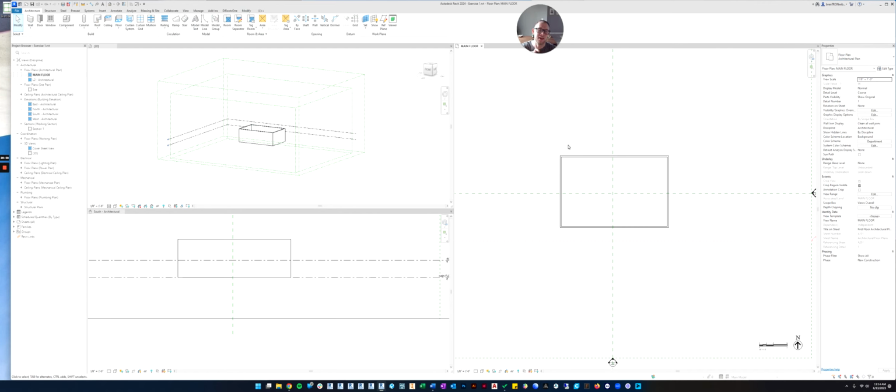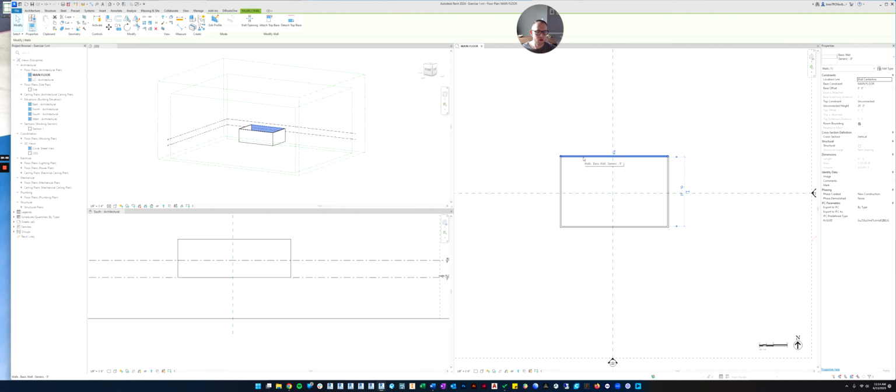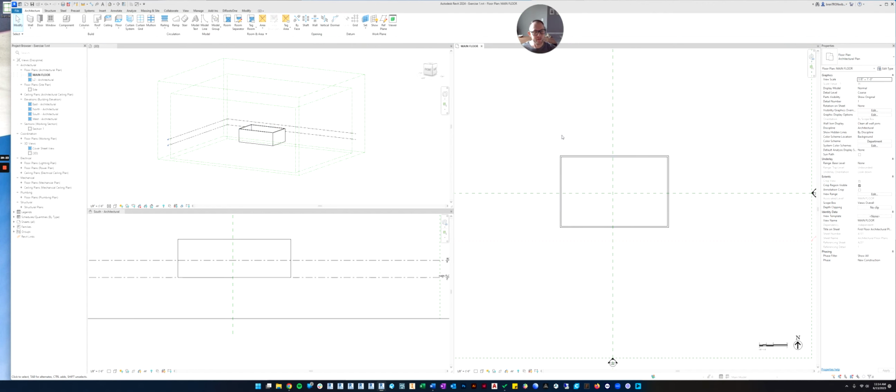And here, let's talk about mass selecting again. I taught you before that you can click a wall, or click something, and if you hold Control, you can add things to your selection. So that's one way of getting all of the walls. Let me teach you a couple more that are handy. Different types of selecting come in handy at different times. So that's the basic way of doing it.